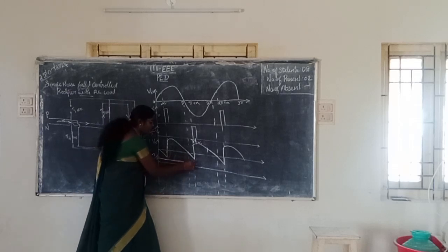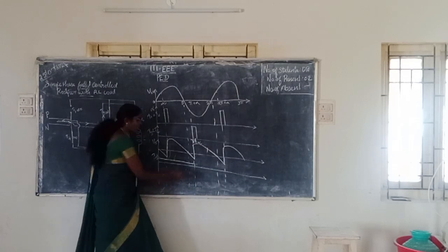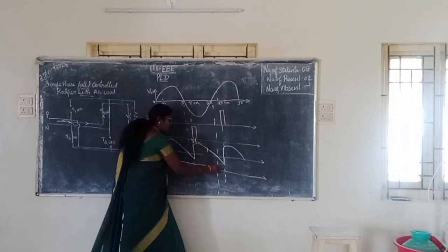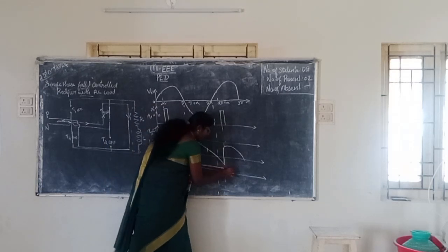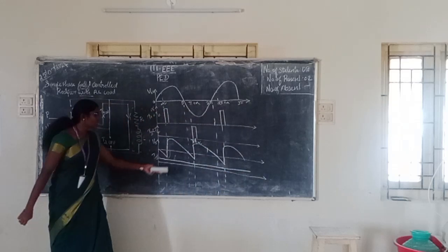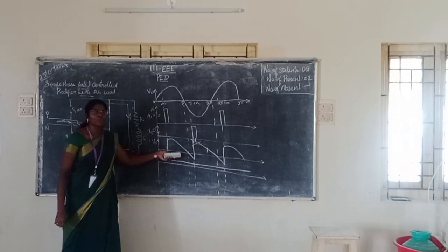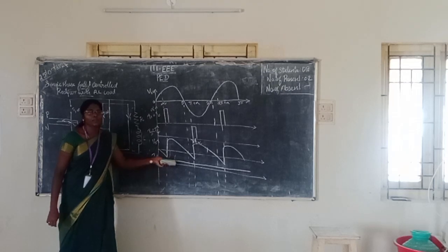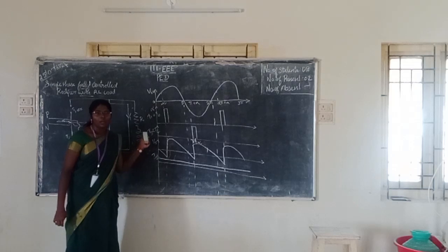Likewise, during the negative half cycle, since there is a supply voltage, the current will flow. So the current waveform is continuous. This is what we need. The direct current should be like this. It should not go to 0 or to the negative side, so that the ripple can be much reduced compared to the R load.